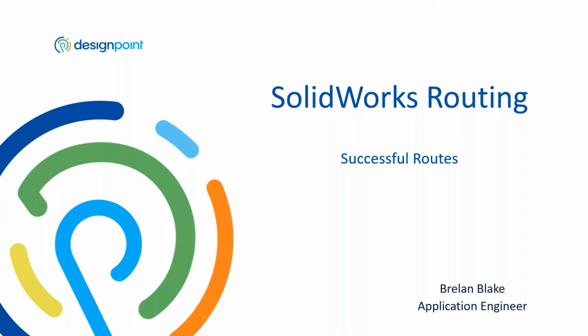That's one way that you can create a custom component. The second way you can do it is you can create models from scratch. So any kind of SOLIDWORKS models that you start modeling, they could be any kind of part. You can even start from an assembly. You just have to save it out as a part just to reduce the size. But then you can use some of those components to create your C points and some of your route points. And all of these components will have to go through the routing library manager in order to be route components. And then you can put them into your design library or onto your Vault. It all depends on the company standards.